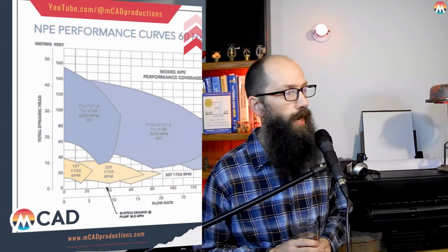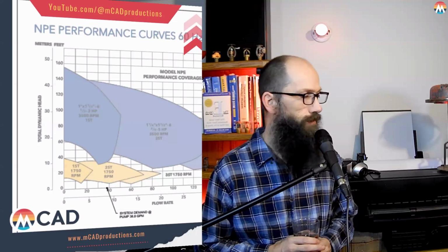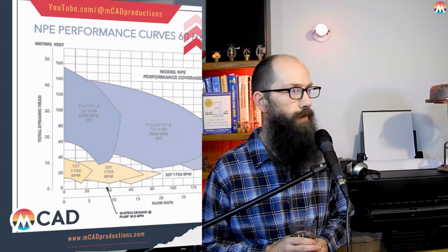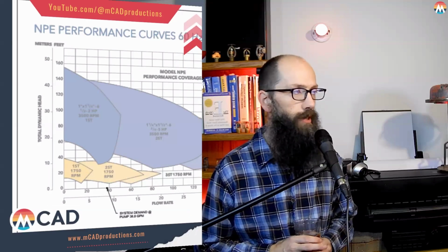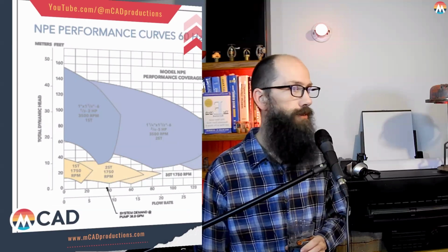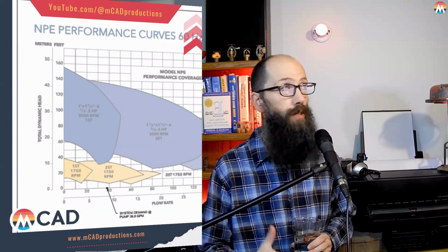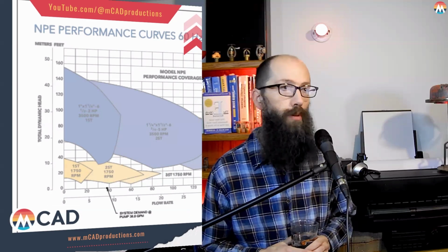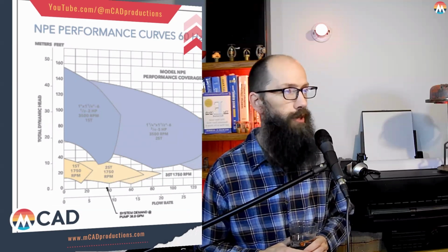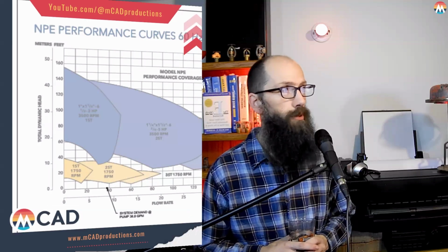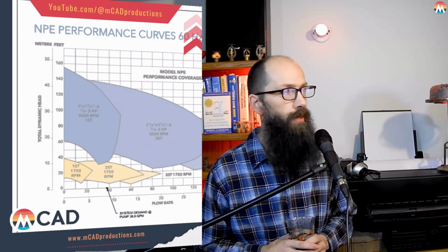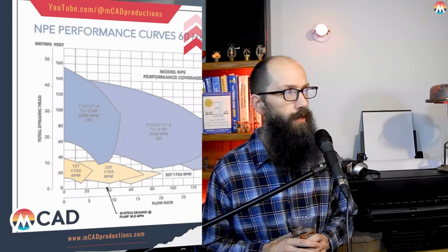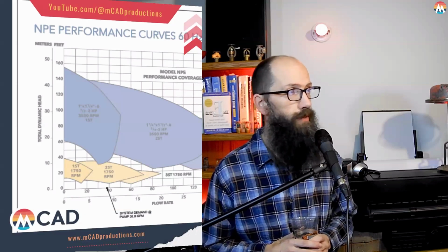Oh yeah, here is a job I just recently did in another state where they don't have home hydrants there. They don't have easy access to those. And so they sent me this pump curve for the pump that they were using, what is available there. And I put this pump curve on the drawing and showed where the system demand lies. And it's well below the availability of the flow of these curves.